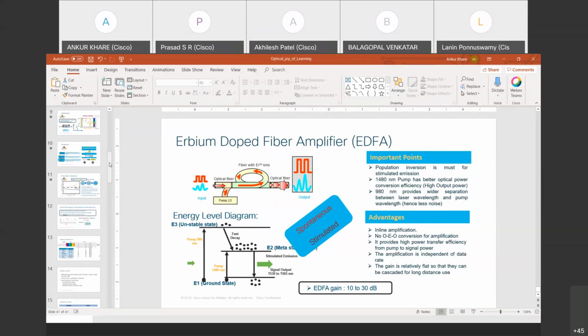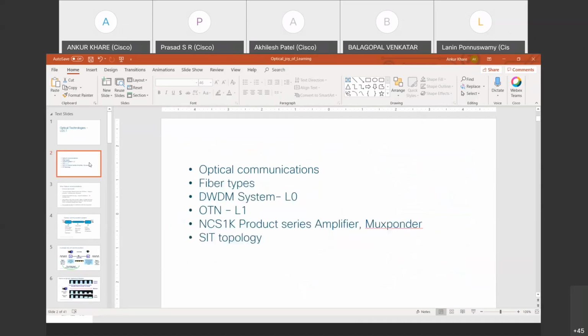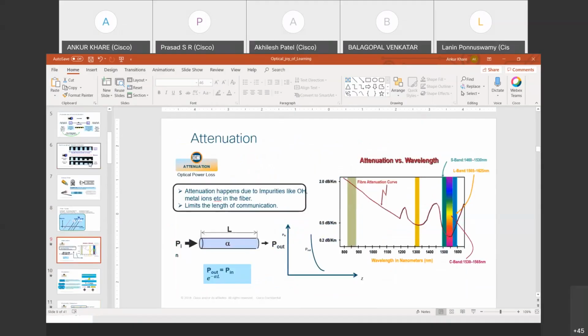Yeah, we have fiber spools to simulate those long distances. Mostly we have 25 kilometer, 50 kilometer, and 75 kilometer fiber spools in the lab. We insert those for performance testing. When you talk about L0 testing, mostly all the performance testing happens in the Italy lab. There is a device called OSA, an optical spectrum analyzer, which is used for testing these properties, whatever we discussed in L0 testing.